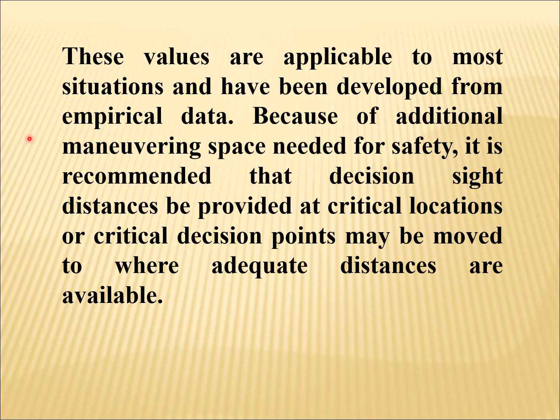Because of additional maneuvering space needed for safety, it is recommended that decision sight distances be provided at critical locations, or critical decision points may be moved to where adequate distances are available.